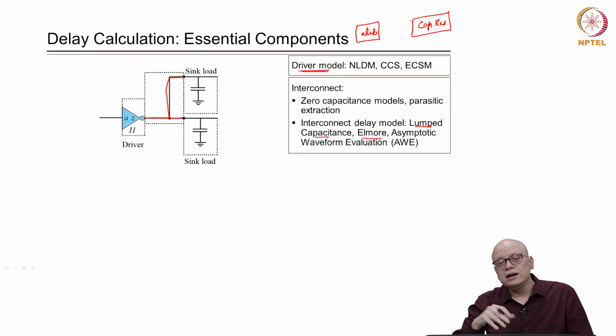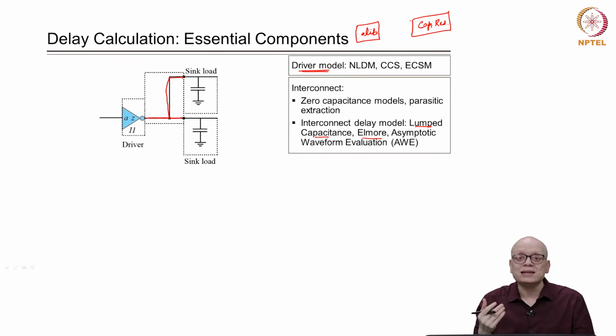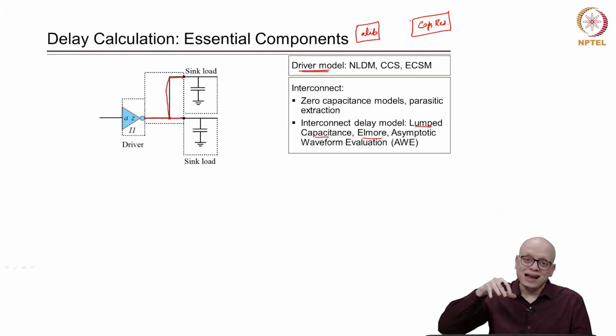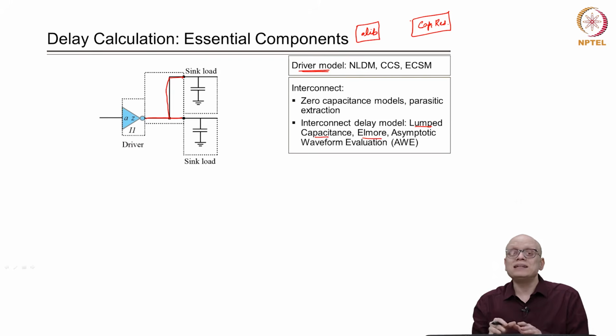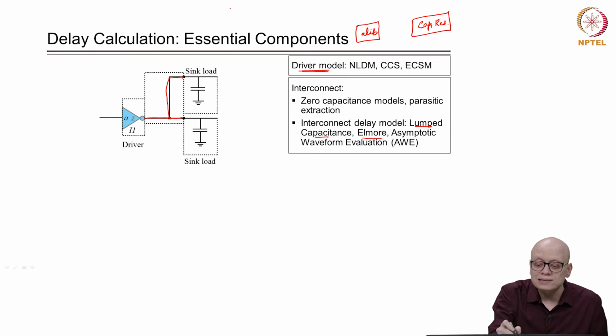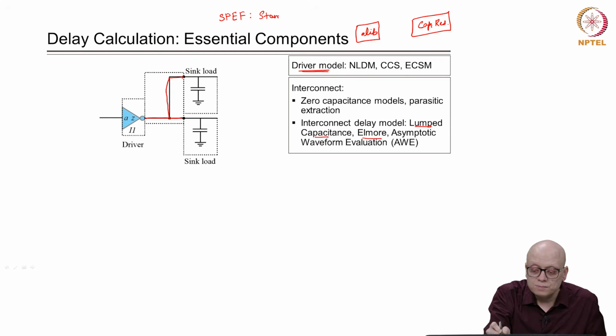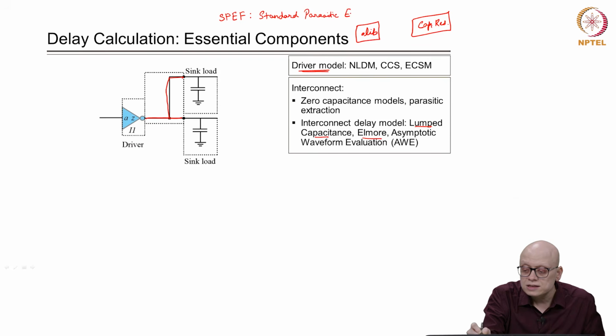From the layout, a parasitic extraction tool can extract the capacitance, represent it in an RC model, a resistance-capacitance model, and put it in a file known as the SPEF file, which stands for Standard Parasitic Exchange Format.